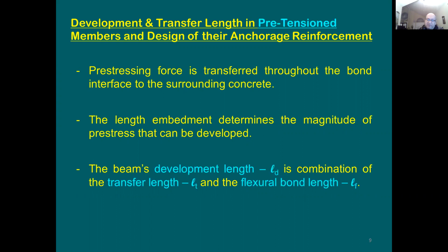After you apply all the pre-stress forces, you're going to be taking this beam, and then after this, you're going to be applying the service loads. Service load means that later on you'll apply the additional dead load, which we call here superimposed dead load, and also you're going to be applying here the live load. To transfer the first amount of pre-stress force that you put in there, you need the distance L sub T. For the additional forces, you need also L sub F. Total length is going to be equal to L sub T plus L sub F. We're going to see empirical equations for that.